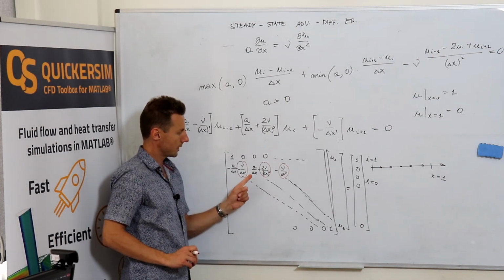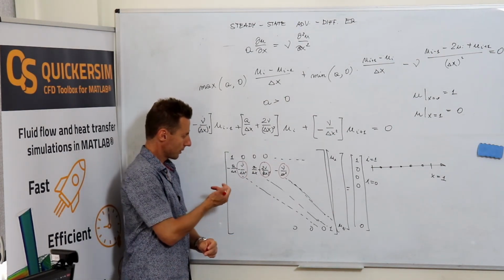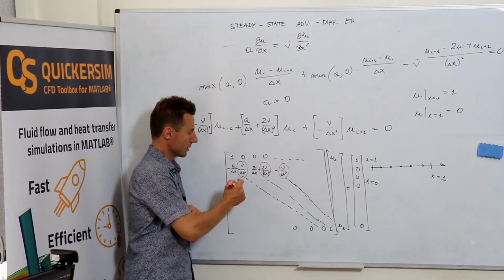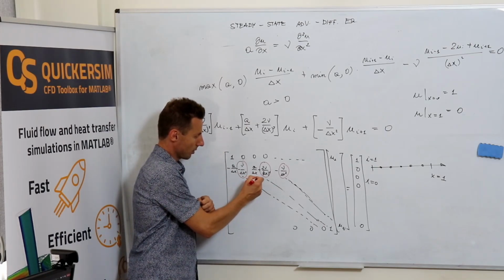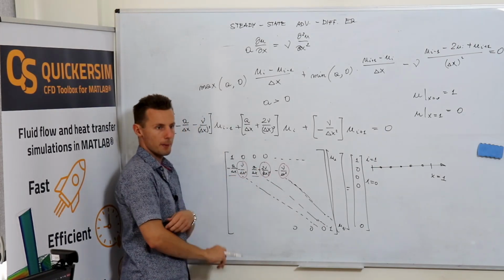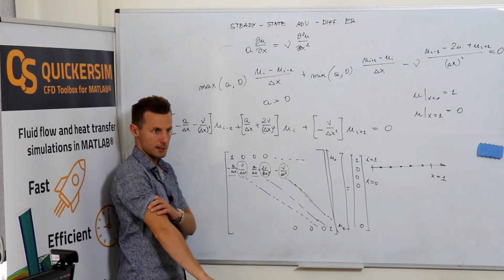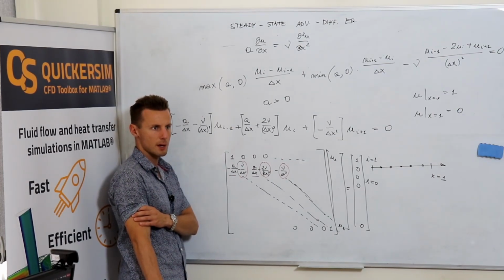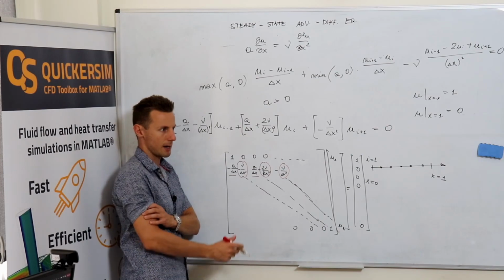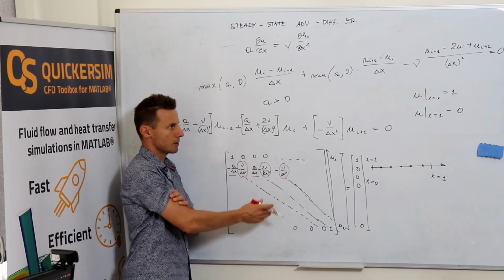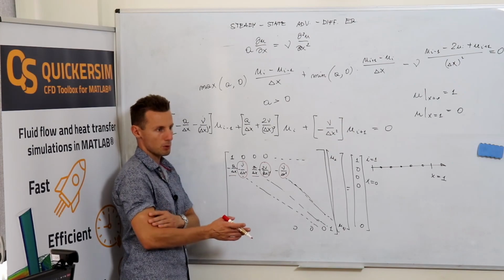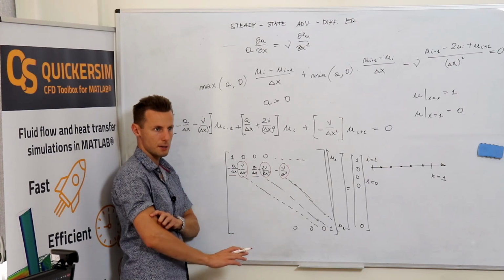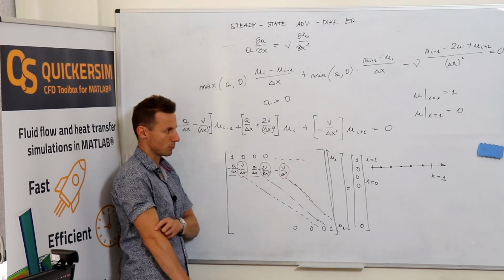However, what is introduced by convection always leads to antisymmetric matrices, because you would see that you've got velocity and negative velocity. It's always the case. Whatever discretization you take, whether finite differences, finite volumes, or finite elements, diffusion will lead to symmetric and positive definite matrices. The convection will always lead to antisymmetric matrices.